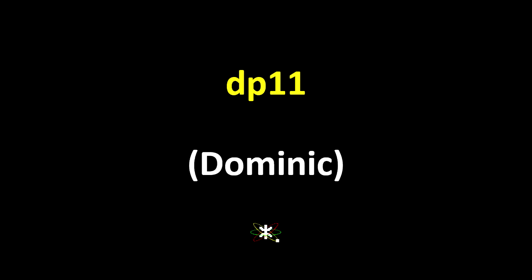Basically what you end up doing is, in the I/O cell, you end up with a little feedback path, and so it just oscillates to try and track the composite video. You don't do anything in the clock domain, but that oscillation you then feed across the FPGA, which is good at that, and then you filter it back out again. And that gives you back your composite video again. That's amazing.